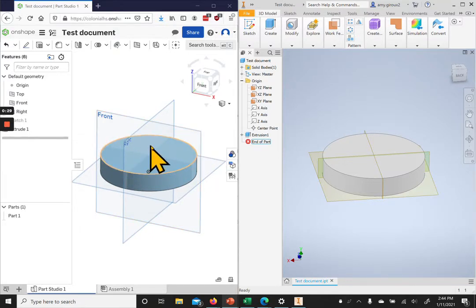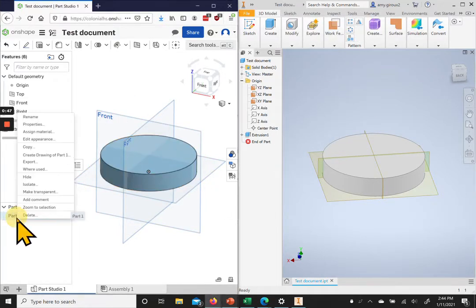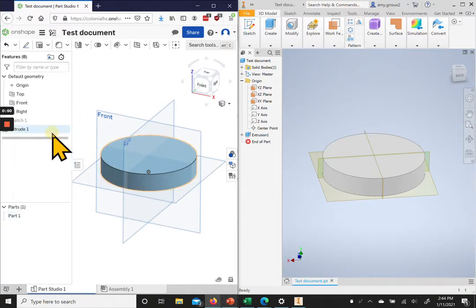So, first of all, with our materials, remember a lot of times we have to have a changed material to be able to create or have a mass of what our object is. In Onshape, remember that if we right click on our part, down in our parts list, we can assign a material, and eventually a materials window should pop up and we can choose our material there.